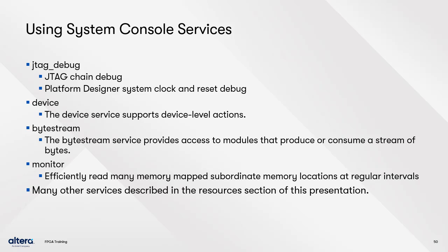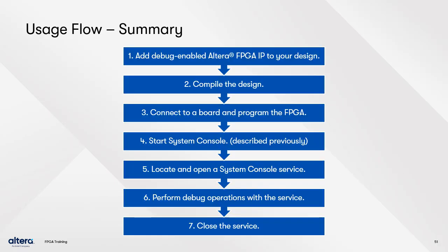tests easy. This slide displays the basic flow when opening and using services provided by the System Console inside Quartus Prime software. After ensuring that the necessary components are added to your system and your board is properly configured, launch System Console and it'll be ready for interactive usage.